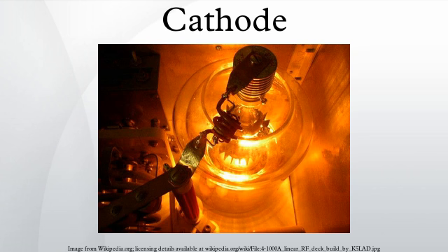Diodes: in a semiconductor diode, the cathode is the n-doped layer of the p-n junction with a high density of free electrons due to doping, and an equal density of fixed positive charges, which are the dopants that have been thermally ionized. In the anode, the converse applies. It features a high density of free holes, and consequently fixed negative dopants which have captured an electron.